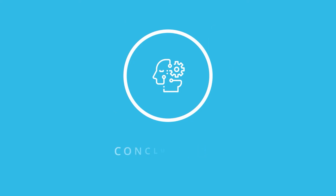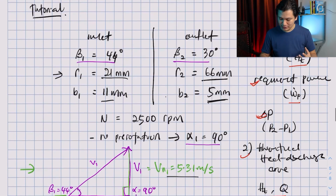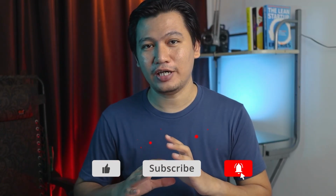So you've done a lot here, right? You've got the discharge, you've got the theoretical head, required power and delta P, and you also have the discharge curve, right? So please try and do this tutorial again and again and relate what we've been doing now with the equation that you've derived in the previous lesson. Because whatever equation you've derived, you're going to use it here. Also remember that the key is actually the velocity triangle itself. If you can master the technique of drawing the velocity triangle, you can find the answer to any question.